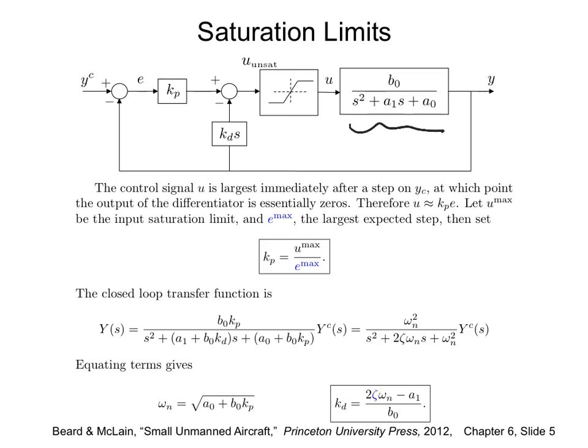So it's a second order open loop transfer function. And your U, because it's PD control, it gives you whatever the error multiplied by Kp. That quantity can be any quantity, right? If you're really far away from the desired value, then it will be a huge value, which your system is not capable of. So you are putting a saturation block here.